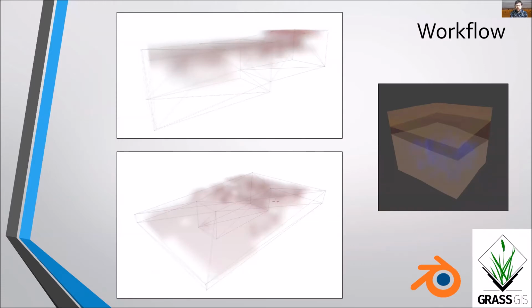An alternative approach is to consider the relationship of the artifacts in 3D using 3D point densities. 3D point densities exist as part of the GRASS GIS software suite, but are difficult to use and incorporate with other GIS data. This is mainly because the visual outputs are in a voxel format, which is not currently supported by any GIS interface, and the rendering of which is only possible in specialized renderers or versions of Blender 2.79 and lower. However, thanks to the Blender GIS add-on, we can bring GIS data to Blender, where voxel data can also be rendered, as can be seen by the density cloud in front of you.